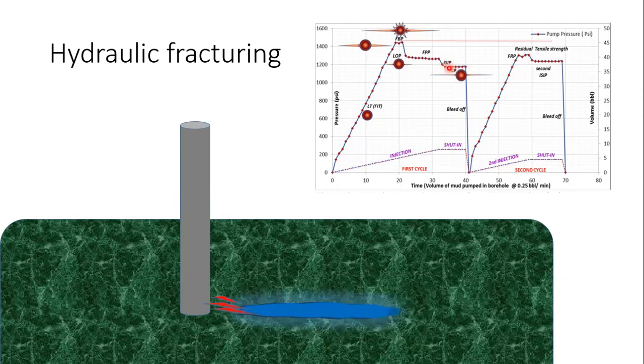So initial shut-in pressure will hold for some time, and after that it will start to decline suddenly. Abruptly, we can understand this fracture will start to close, but it will take some time. The time is very important over here to understand the potential capacity of that fracture to sustain, so that the fluid can flow through it to some extent. Then after that, the fracture will close. Once the fracture closes, the fluid which was present inside will be displaced towards the formation.